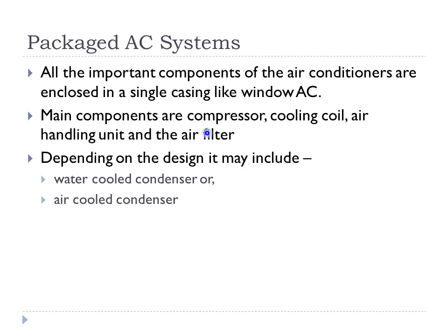Friends, packaged AC system are same as window or split AC system, but the difference is that they are having larger capacity, and that's why these systems are having two arrangement. They may have water cooled condenser or they may have air cooled condenser. Friends, we have seen in case of window AC, the arrangement was having air cooling for the condenser coil. So alternatively, we may also have water cooled condenser, and again we can also have air cooled condenser.